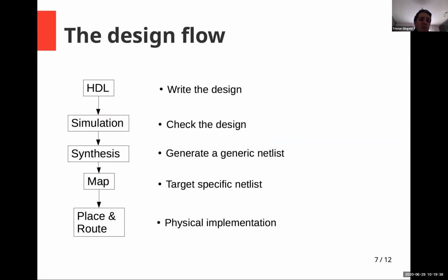So the usual design flow for circuit design, if you don't know it, is starting from HDL. So you still have to write, let's say, the code of the circuit. Maybe you can still use drawing for assembling a large component. And you can do simulation in order to check the design. It's mostly for verification. And if the simulation is correct, you can start to do synthesis.